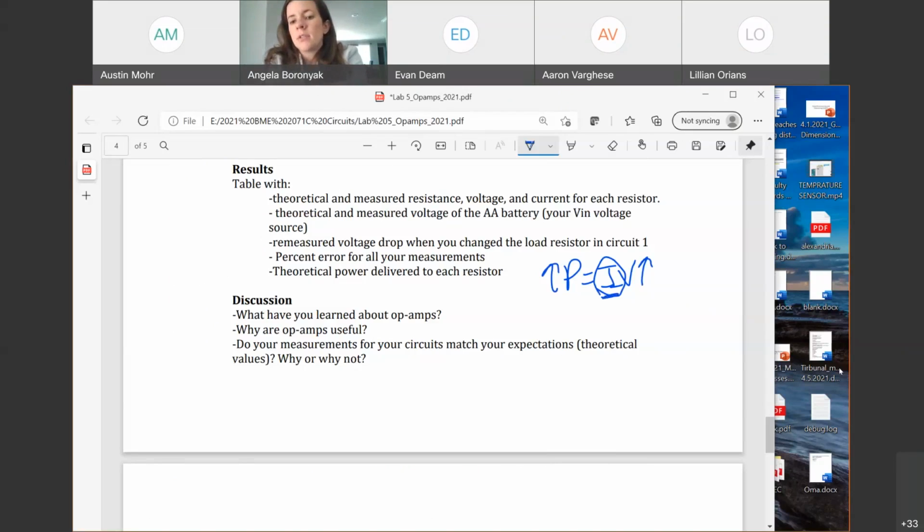The answer is yes, these are tied. So in our other power equations, if we plug in Ohm's law for either current or voltage, we get power equals voltage squared over resistance, where I can see R stays the same. What happens when you change V to P? Or current squared times resistance. So do be careful with that. It looks linear here, but that's only linear if this stayed constant, and it doesn't. For a resistor, if you change voltage, we just said you change current as well.